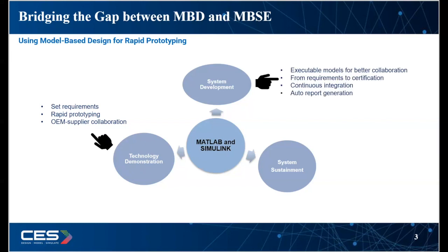Then you can do also with model-based design using MATLAB and Simulink the system development. You design a model that you can use as a ground truth. You can also link the requirements and trace them, and then eventually you can use these requirements with other tools for the certification, for the continuous integration and for auto report generation.